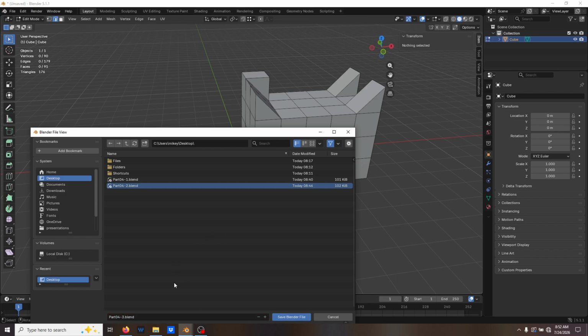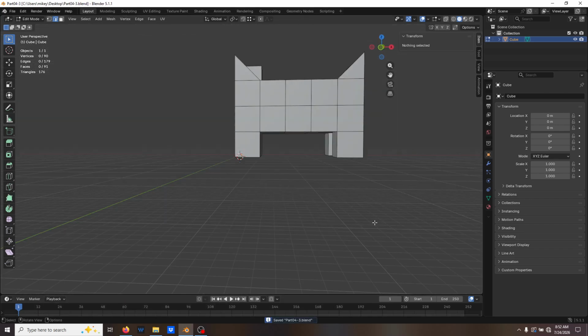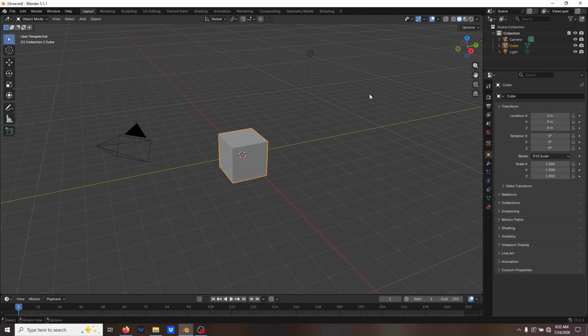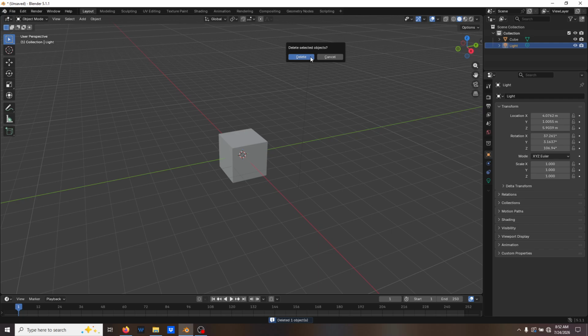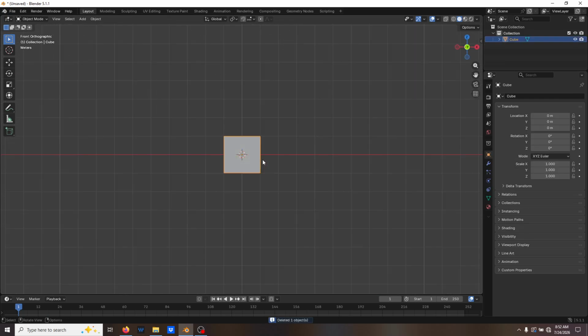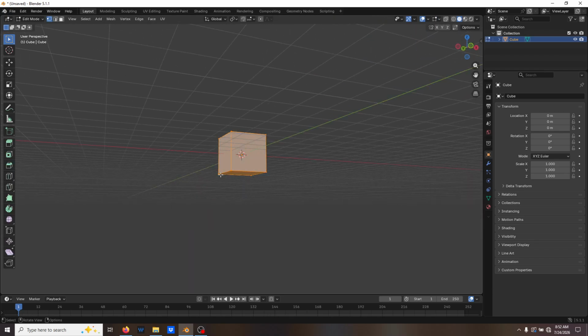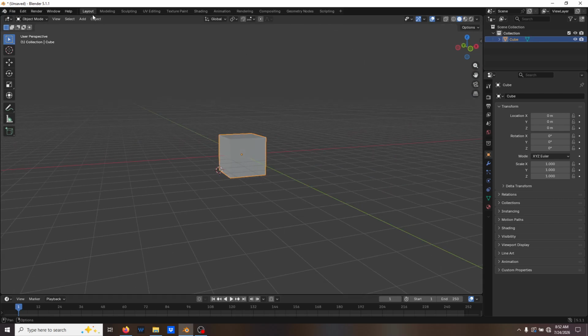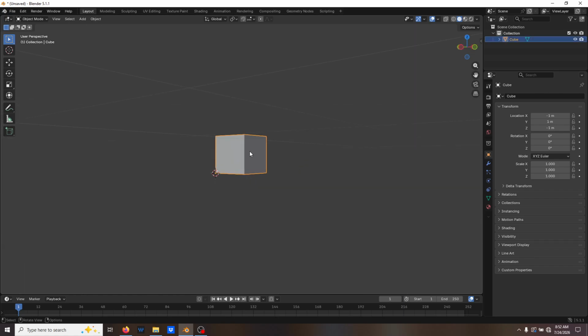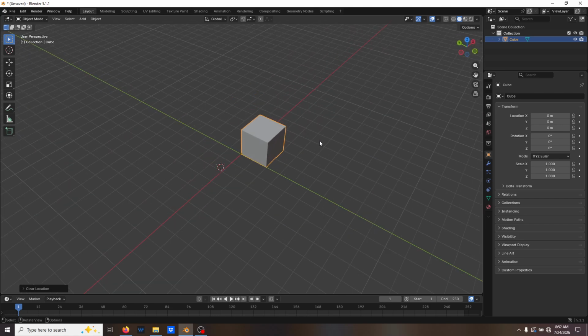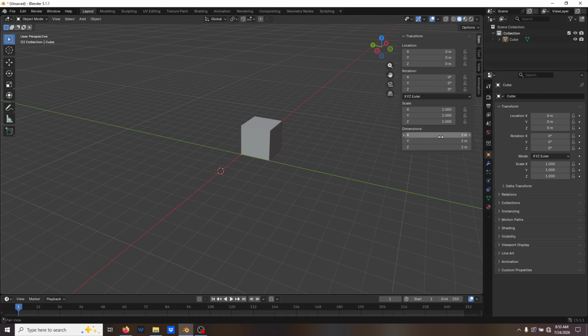Okay, -3 .blend. Okay, and so now one more method I want to demonstrate with this. I'm going to delete my camera and my light source. There we go. I'll go back to this. I want to pull that back corner, go into edit mode, select that, Shift S, cursor to selected, Tab to go back into object mode, Object, Set Origin to 3D Cursor. I go back to that. I will Alt G to move that back to my origin. I'll press N to bring up the transform menu, or properties menu, excuse me.